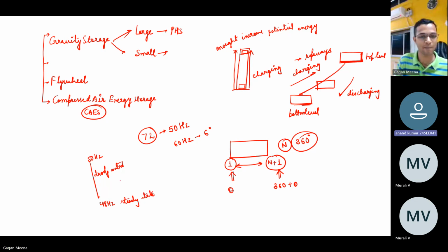But as per the question requirement, the total load demand was not getting fulfilled without overloading the generator. One generator needed to be overloaded. We cannot overload the generator. So shall I consider the maximum loading as per the rating of the generator and load the other generator with what is remaining?